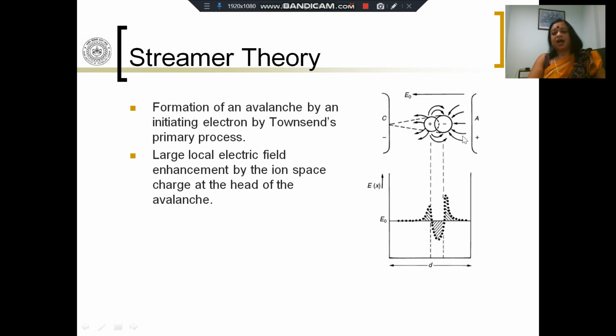Now, when you have a large number of charges accumulated in the volume of the dielectric, these are free charges. Whenever you have a large concentration of free charge anywhere within this volume of the dielectric, we call that space charge. So we have talked previously about free charges. We have talked about bound charges. The third kind of charge that we will talk about in this course is the space charge. Space charges are free charges which are concentrated in very large quantities somewhere in the volume of the dielectric.